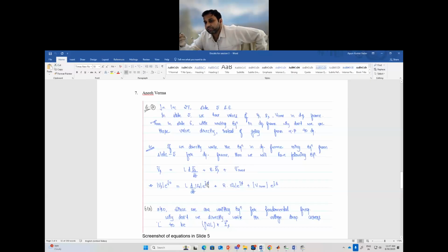But when we define in alpha beta and then go to dq, there we will have the angle component. And why particularly are we going this way? Because any three phase quantity we first represent in terms of alpha beta, and then from alpha beta we define the dq. Similarly, our circuit model will first be defined in alpha beta, which is a stationary frame, and then go to the dq rotating frame.